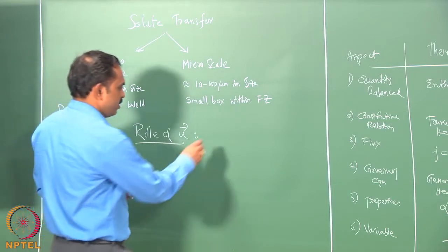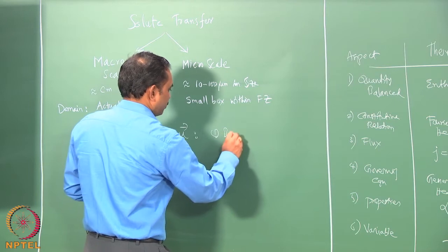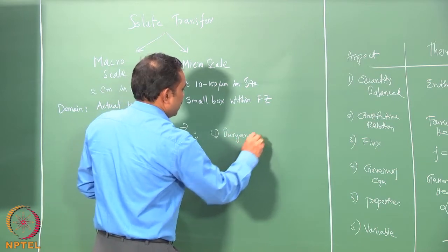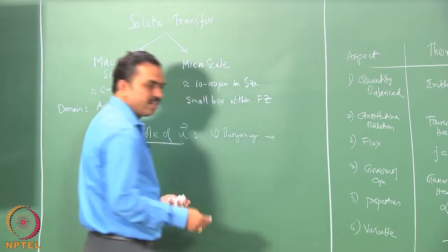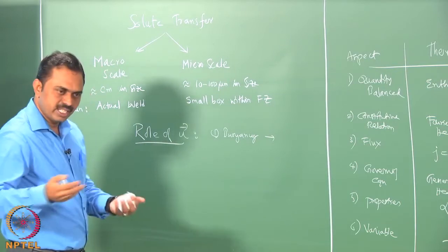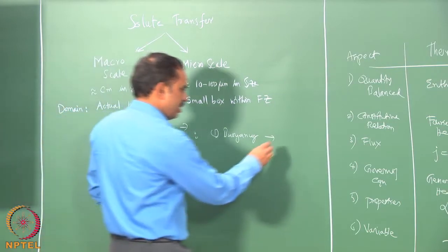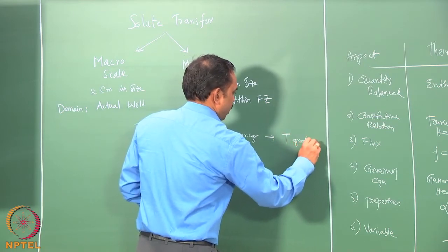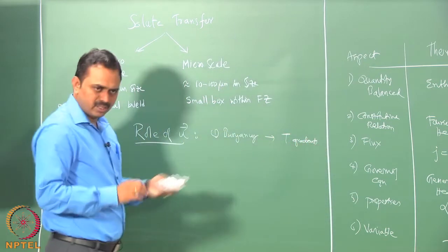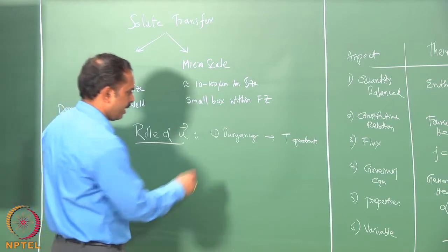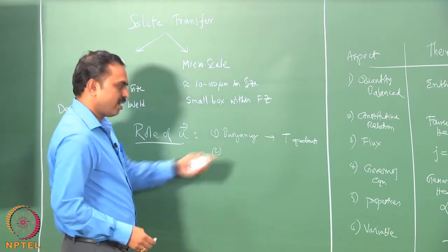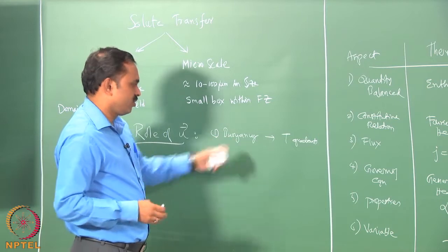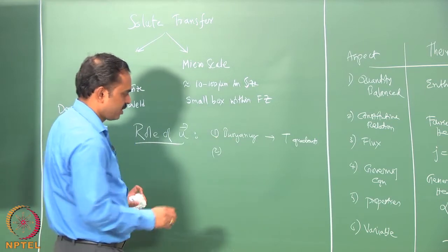The first driving force is the buoyancy, and it is driven by the temperature gradients causing the density gradients, and these do not generally change very much during the welding. Also the strength of convection is not very high in the buoyancy convection mode.